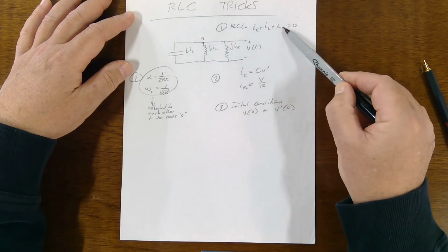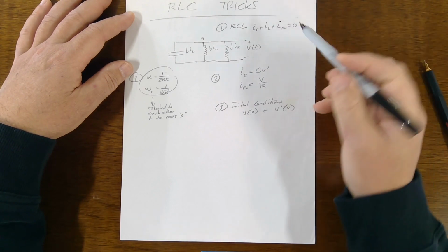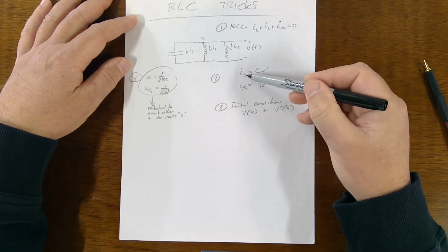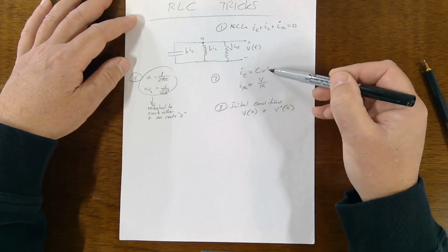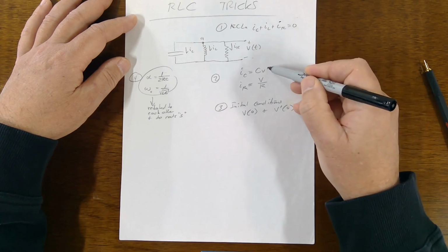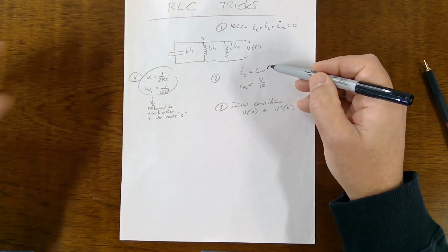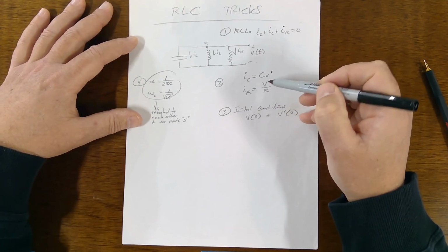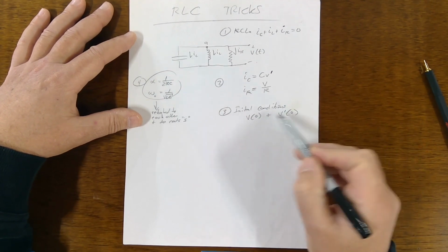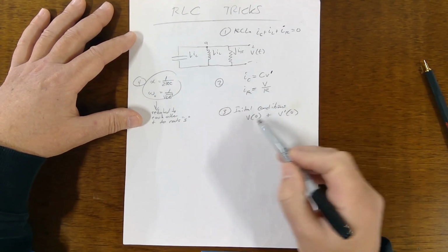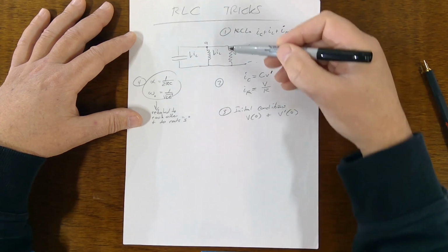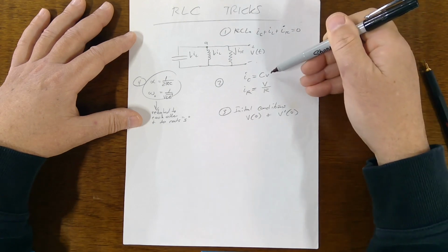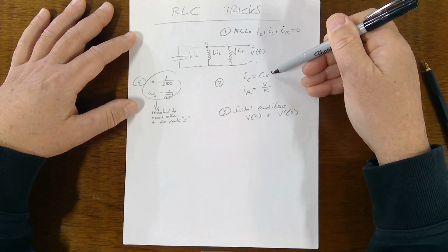We're just going to sum the 3 currents. And the second trick is these 2 guys. I sub C equals C V prime. The current in a cap is C V prime. This prime thing is one of our toolkit equations, right? And the current in a resistor is V over R. That's Ohm's law. The third trick is these initial conditions, which we may be given or maybe have to solve for. V0, the initial voltage across these 3 guys, and V prime at 0, which we might be given. Or you might be able to get from here, right? Here's V prime at 0, right?